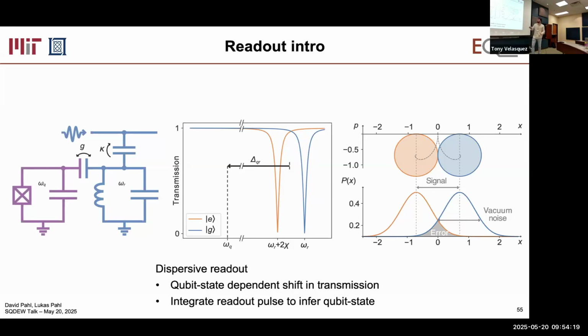In general, we can just look at which frequency of your readout pulse maximizes the separation. So you can form this whole thing while changing where your readout pulse is centered, and the place that gives you the maximal separation is typically how we calibrate this thing. But it's magnitude and phase. In this case, it's mostly magnitude.